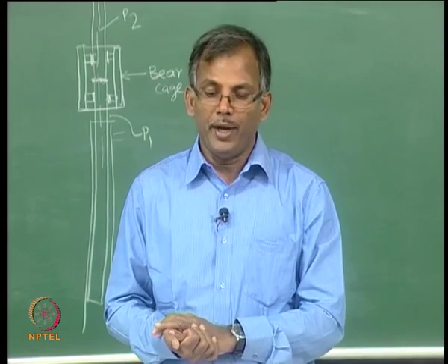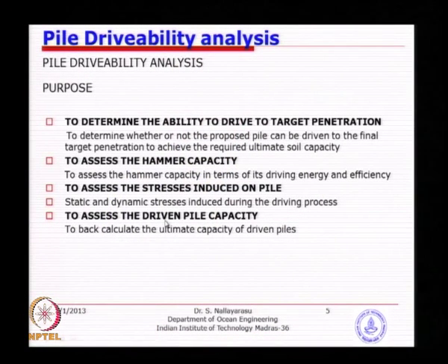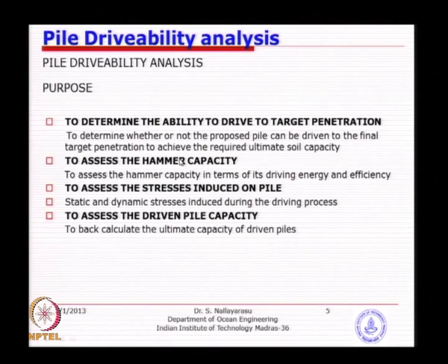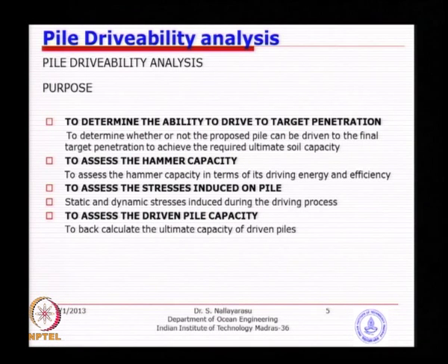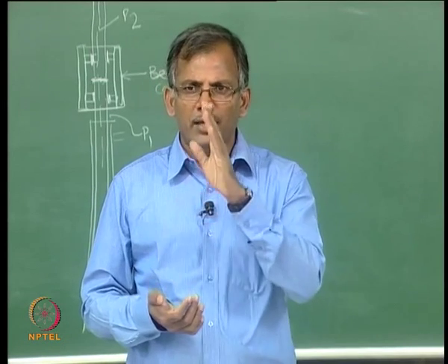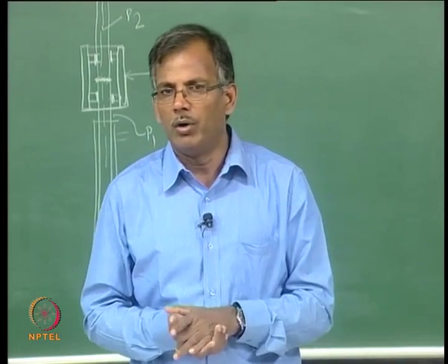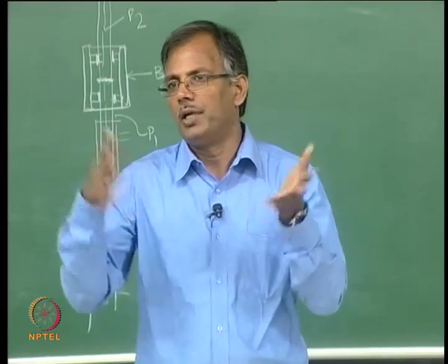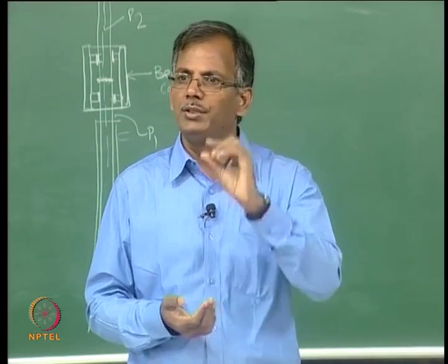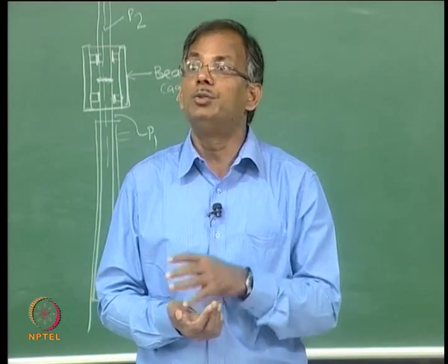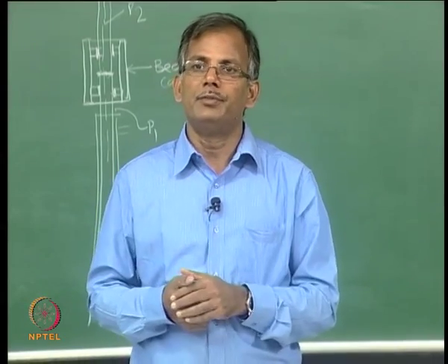So, that is why we may also require a methodology based on pile driving effort. For example, you assessed your required hammer for pile driving, X impact energy, you go offshore and drive, and then during the driving, if the pile is going down very slowly, for example, instead of half a meter per few hundred blows, 300 blows, it goes only by 2 inches, 3 inches, that means the resistance of the soil is higher than what you expected, something which we can characterize.